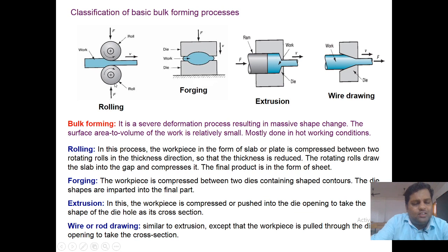Cold rolling is nothing but, without heating, changing the material by compressing it with the rollers, feeding it in between the rollers without heating. That is cold rolling. Similarly, we have hot forging and cold forging. Forging is nothing but applying a certain force for a certain time period using a die to get the shape of a material. For example, spanners are made by the forging process.